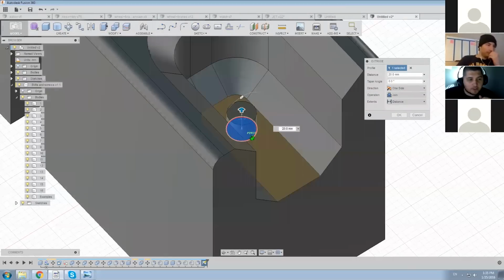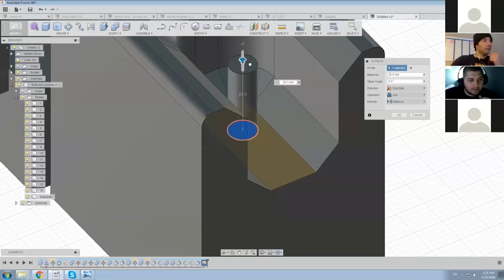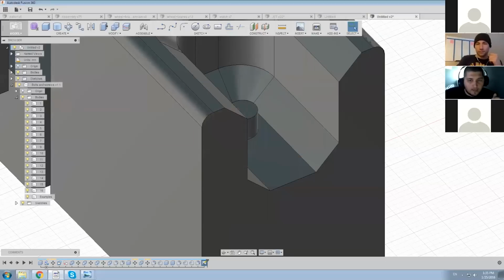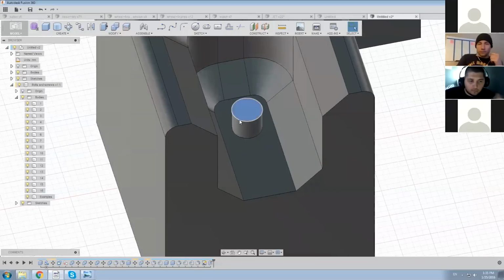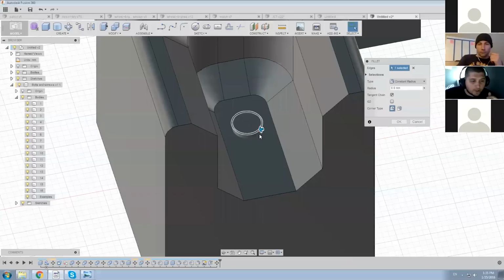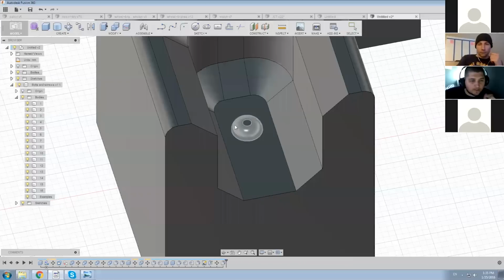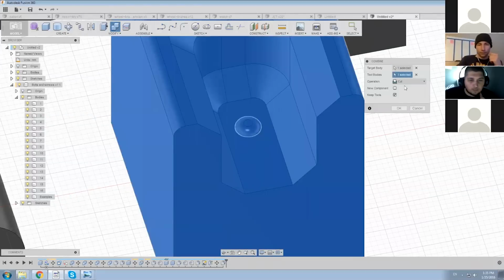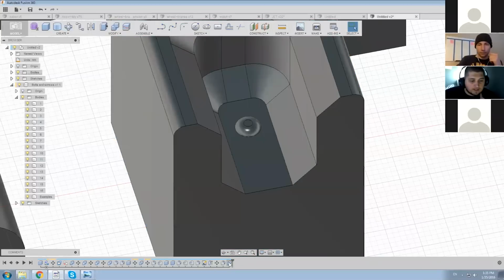So when I drag this shape out, instead of guessing the height or whatever, I can just type it in and say, I want it to be 50 millimeters instead of 60. I want it to be 20, and it will be 20. Yeah. And more than that, and this is something that I touch upon in class, after I'm done with the shape, and this is like a little bolt sitting in there, and I create the cut with it, even after that, I can go back in history, and I can undo.